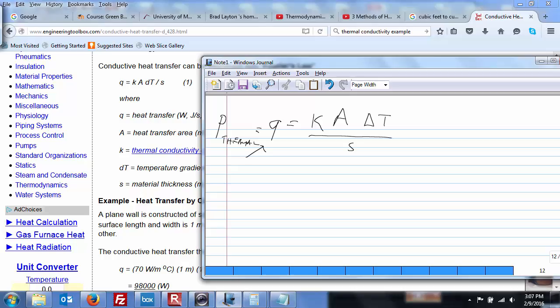We talked about heating degree days. We talked about that 5 or 6 cents worth of heat in your house. This is happening all the time. Like right now, Q is happening, but it's flowing out of this building and out into the outside. If it were a summer day and we were trying to keep it cold in here, Q would be pointing the other direction. At some point, it doesn't go either direction because there's no delta T. It's the delta T that drives it.